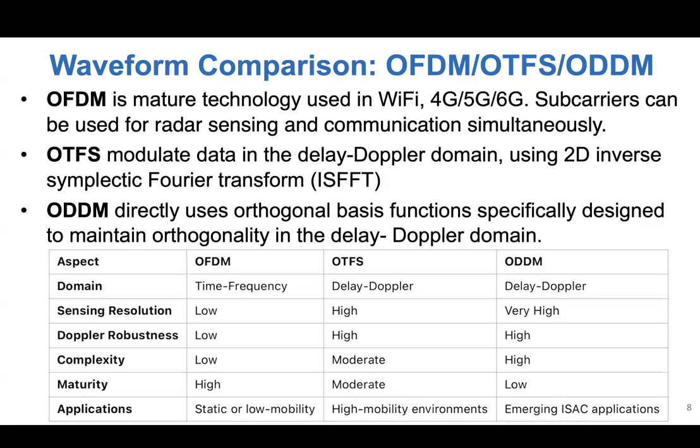And OTFS works in the delay-Doppler domain. Basically, they use the 2D inverse symplectic Fourier transform to transform from the time-frequency domain to the delay-Doppler domain. So in this case, they are very good at high-speed scenarios.